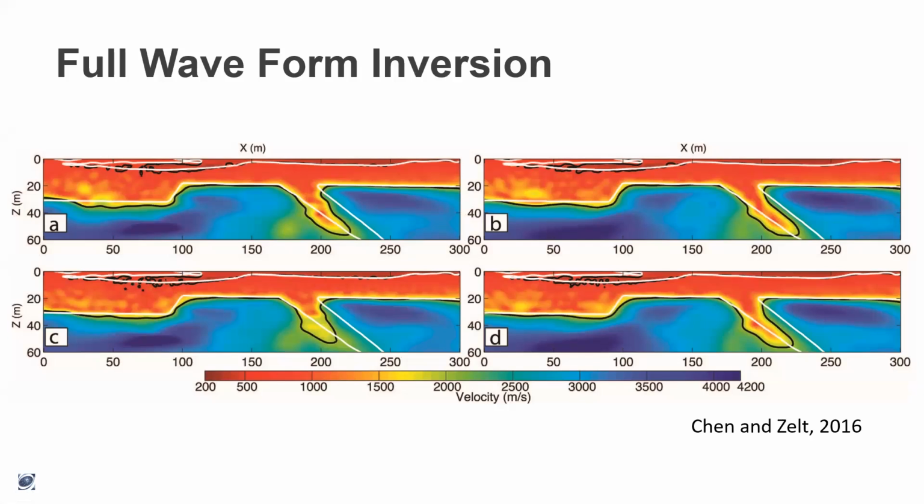Given that there's so much benefit to using full waveform inversion, you might be asking why it's not used in commercial software. The big thing is that noise issue. I've probably done 100 seismic refraction surveys at this point, and I would guess that 20 of them had data good enough for full waveform inversion.